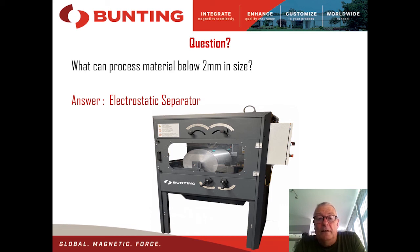And the machine to consider for those sorts of applications would be an electrostatic separator, whose operational area and operational particle size for removing conductive from non-conductive particles is between 4 millimeters down to about 100 microns in size. So they work perfectly well below 2 millimeters in size and will separate out copper from plastic, aluminium from plastic materials and glass and things.